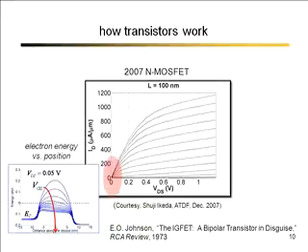Now, you apply a voltage to the gate, and it lowers the electron energy. The energy of an electron is minus Q times voltage. So you apply a positive voltage to the gate, it lowers the electron energy. These are electron energy plots. It pushes the barrier down, and it allows current to flow. And what you see here in low VDS is more and more current flowing. And when you push it down and get a lot of charge in the channel, you can see a uniform slope, which means a uniform electric field. It just behaves like a voltage-controlled resistor.